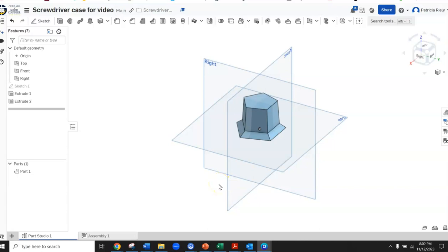All right, next. Now it says time to use the loft command. Also another new command. From the top of the object, offset a work plane, and then add a sketch to the new work plane. Okay, so that's something new for us. So we're going to grab a work plane, and that's here.